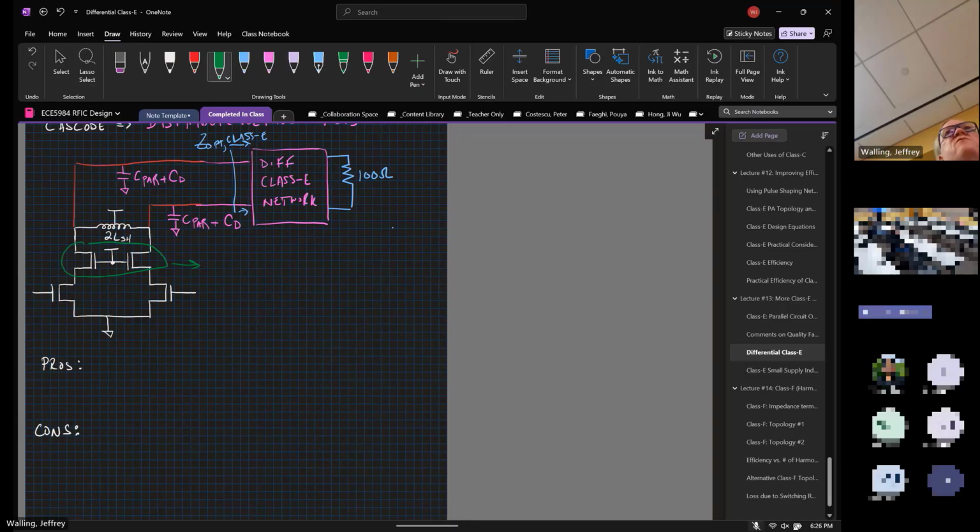So if you want to distribute more voltage stress across those two devices, you can make these thick gate IO devices. They don't need to be fast. And in your particular process, if you're looking in the CMOS 22 FDX library, you'll see FETs that are called EG NFET. The EG is, I think, extended gate NFET or something like that. But anyhow, it's a higher voltage tolerance device, so you can use it there and distribute stress.